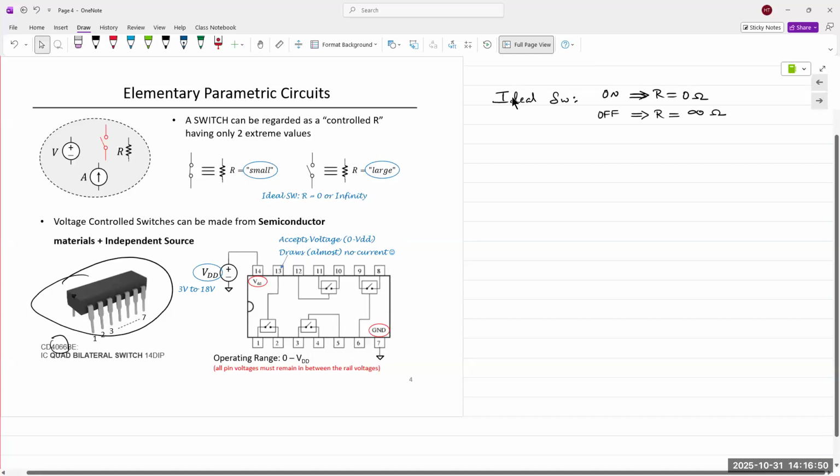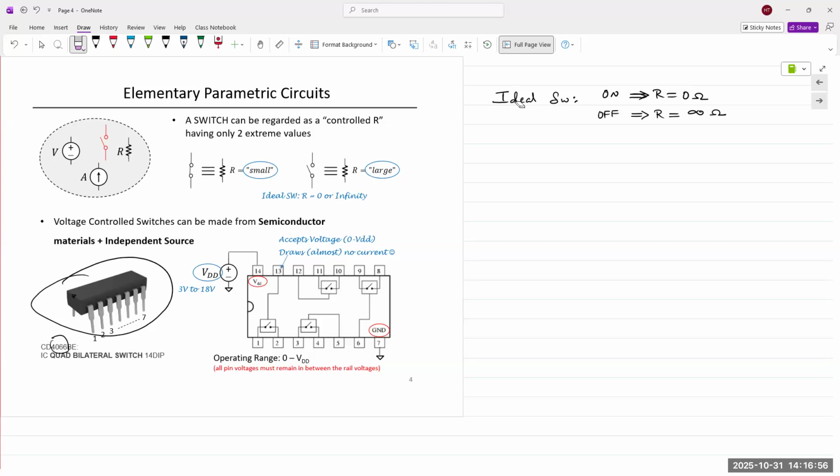Most of these logic circuits or logic microchips, which are 14 pin, pin 7 is always ground, and then positive voltage is always applied to pin number 14 without fail. Okay, it's pretty standard. Pin number 7 is always ground. Pin number 14 is the supply voltage. All right.